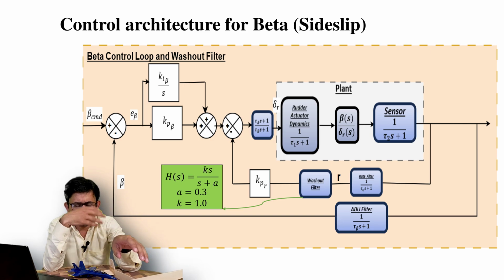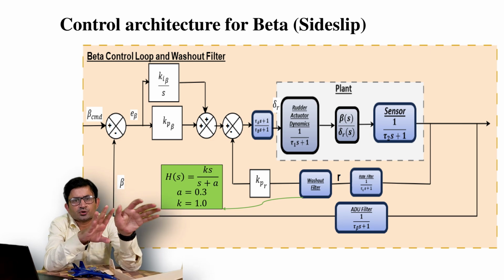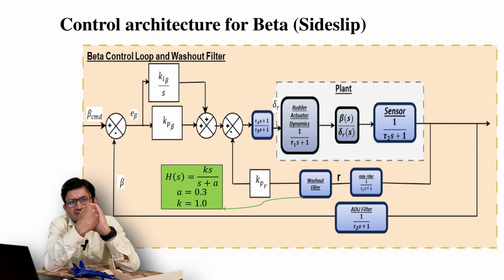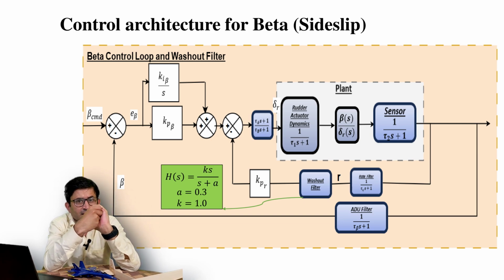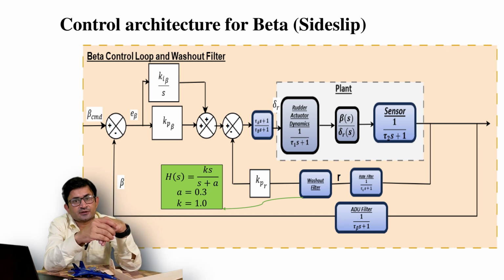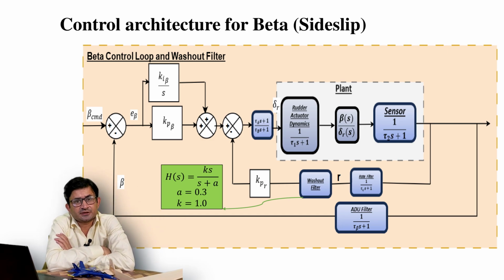If you go more in depth, in the aircraft lateral case you have three modes: Dutch roll mode, pure roll mode, and spiral mode. Generally, the spiral mode is very slow. In the majority of cases, it is unstable. It generally lies in the right half of the plane, close to the origin.